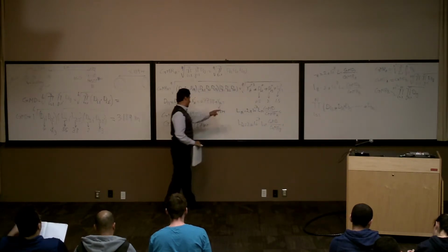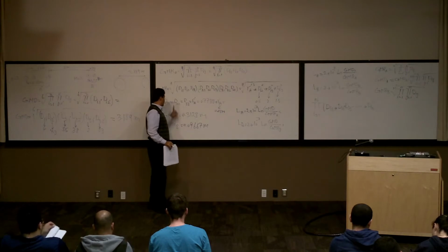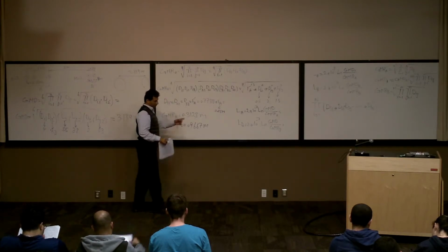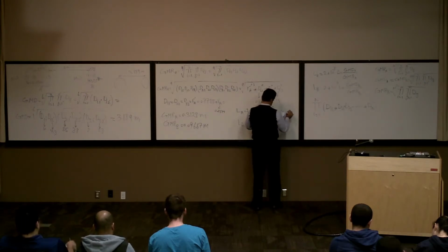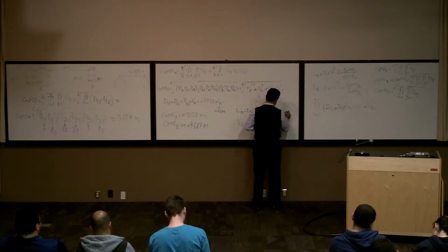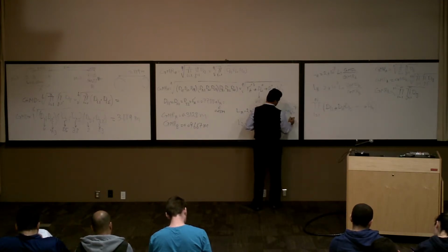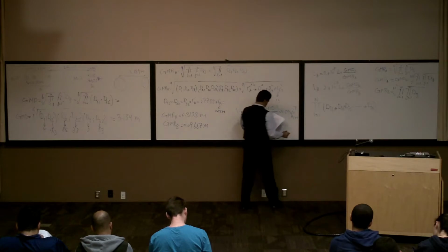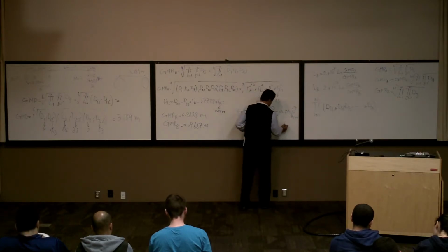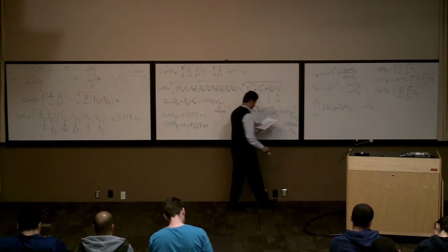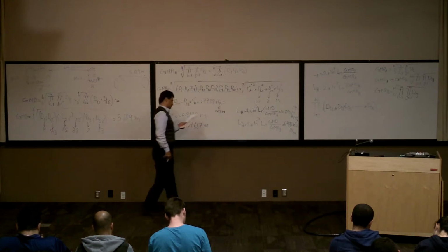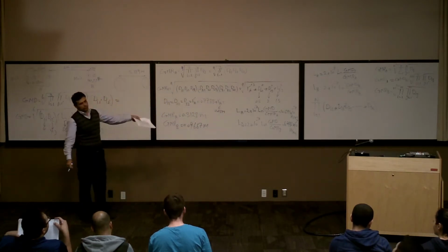So you have all these values. You have the GMRA, GMRB, and GMD. If you replace them here, LA is going to be 4.644 times 10 to the power of minus 7 Henry per meter. And if you do the other one, it's going to be 6.992 times 10 to the power of minus 7 Henry per meter. If you want the total inductance, you should add them together.